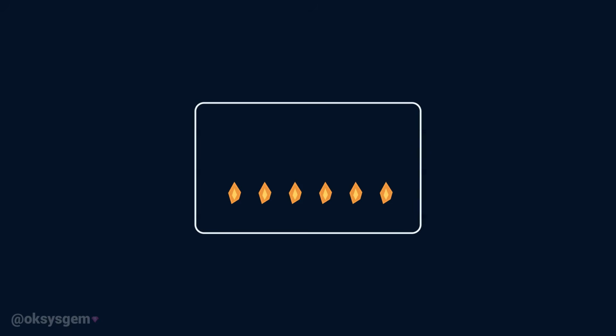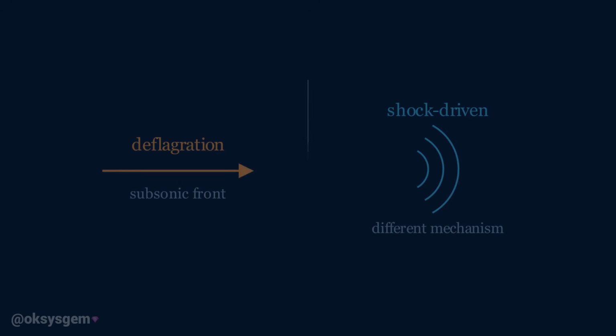However, when the same basic process happens inside a confined space, expanding hot gases can create a rapid increase in pressure. The result can become an explosion. The important feature is that the reaction front itself remains subsonic. The pressure created by the expanding gases can still be dangerous, but the reaction does not propagate as a shock wave. This makes deflagration fundamentally different from detonation, even though both may look like extremely fast burning from the outside. In chemistry and engineering, the speed and mechanism of the reaction matter more than the appearance of the flash.